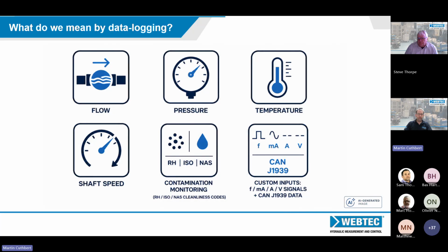We know that downtime in hydraulics is often linked to contamination and to oil quality. So monitoring the contamination or relative humidity is often another piece of information, particularly on test stands and the like, where that's also really useful to pull into the data logger.